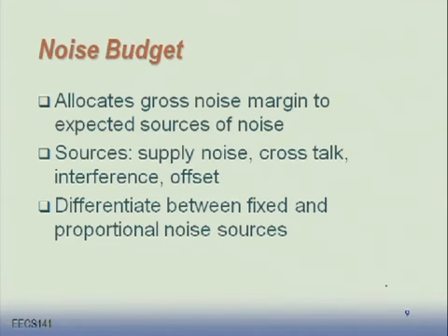If you get really unlucky, it can happen that there can be tens of millivolts and that throws off some of your noise margins. It rarely happens, but it can happen. That's one of the things. It's a popular topic of research these days. You hear a lot about it in conferences because it freaks out SRAM. Your nice SRAM cell is sitting out there, perfectly remembering that it was storing a 1 or a 0. Then a little bit of a random telegraph noise event comes and throws off your SRAM cell.